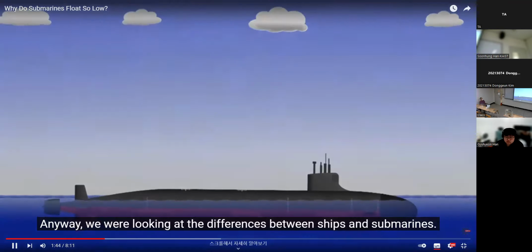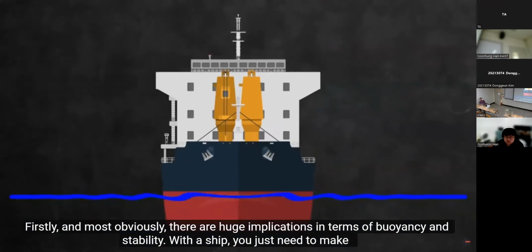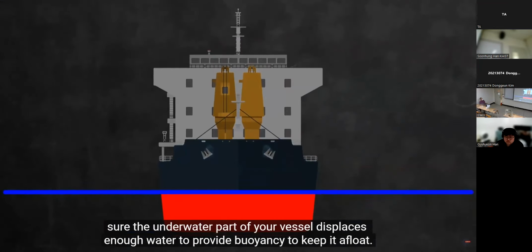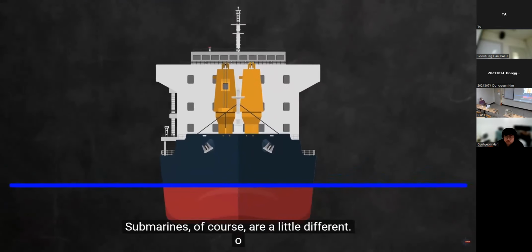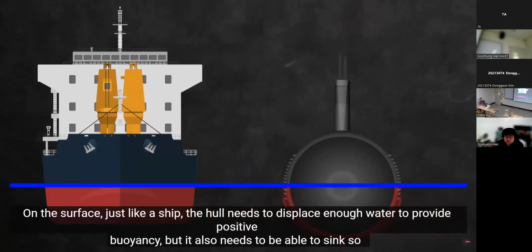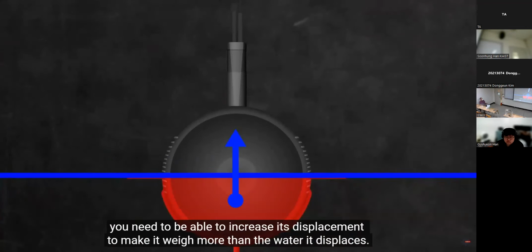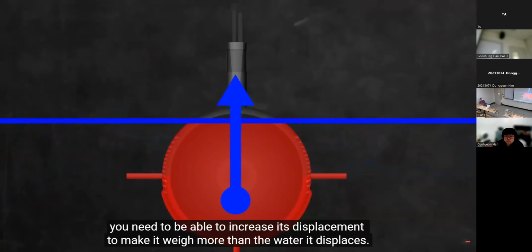Firstly, most obviously, there are huge implications in terms of buoyancy and stability. With a ship, you just need to make sure the underwater part of your vessel displaces enough water to provide buoyancy to keep it afloat. Submarines, of course, are a little different. On the surface, just like a ship, the hull needs to displace enough water to provide positive buoyancy, but it also needs to be able to sink, so you need to be able to increase its displacement to make it weigh more than the water it displaces.